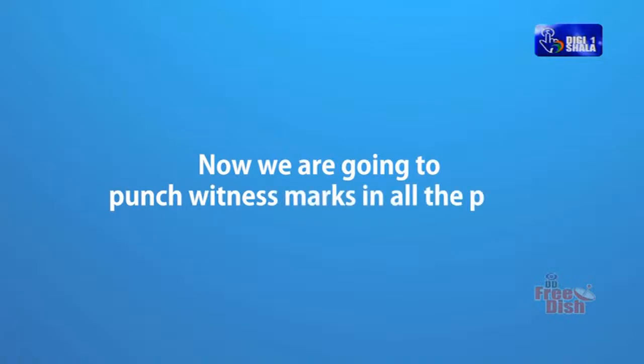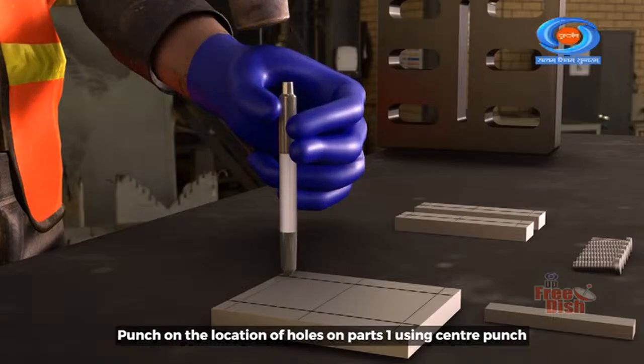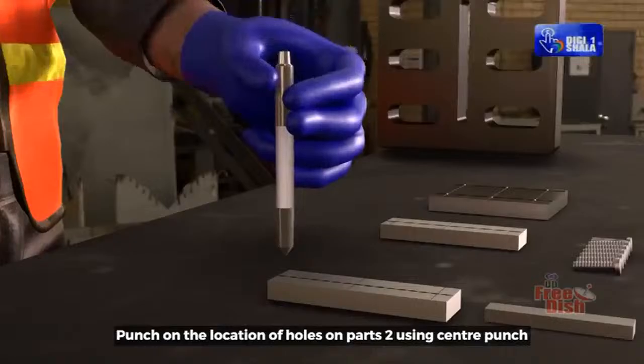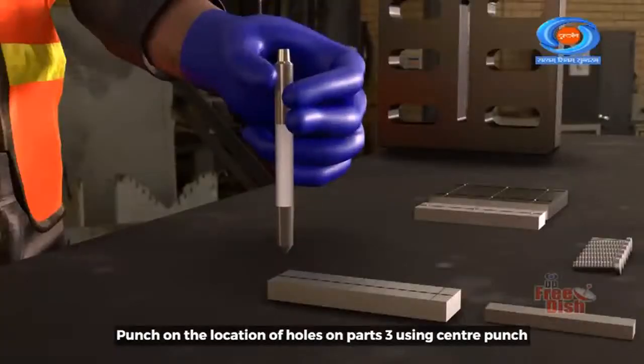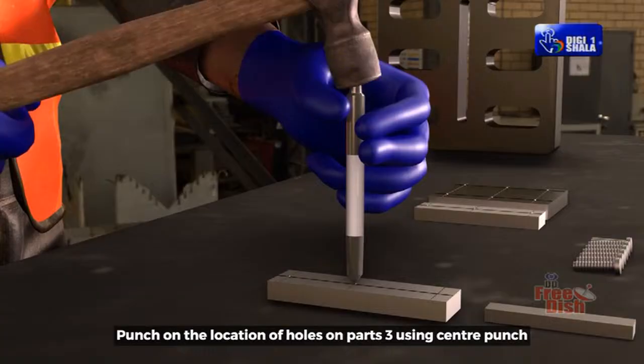Now, we are going to punch witness marks in all the parts. Punch on the location of holes on part 1 using center punch. Punch on the location of holes on part 2 using center punch. Punch on the location of holes on part 3 using center punch.